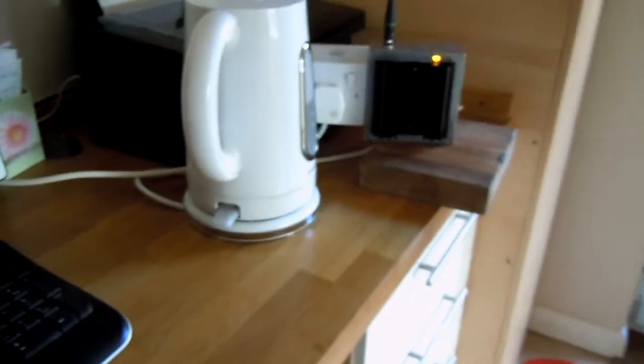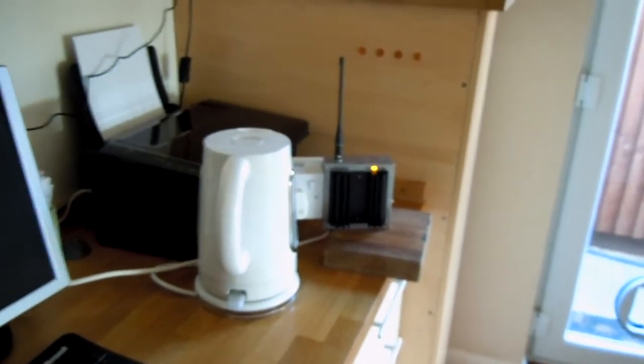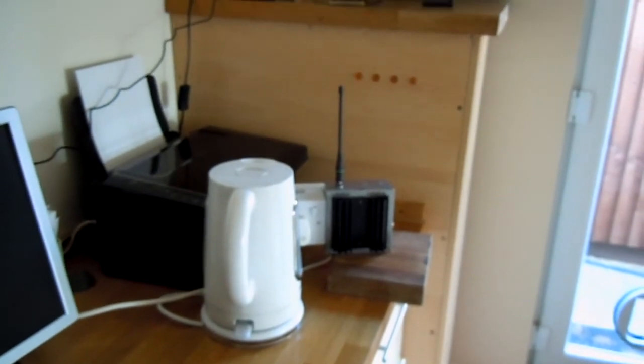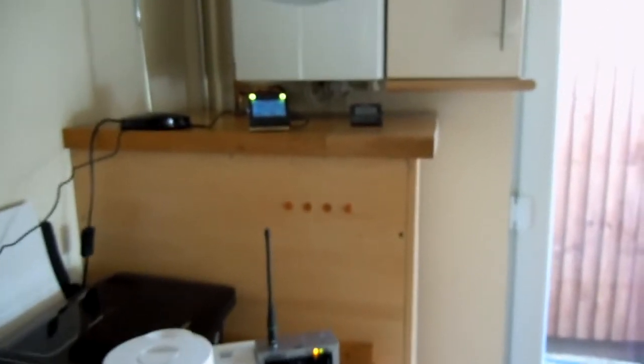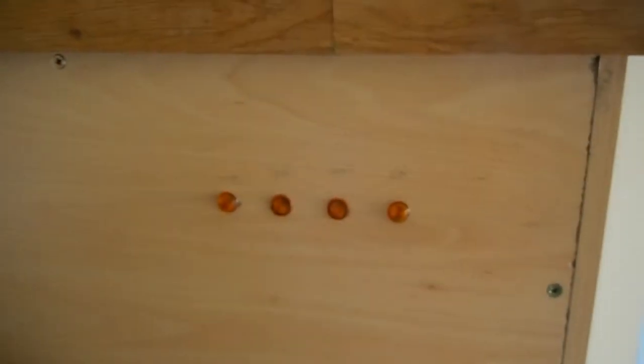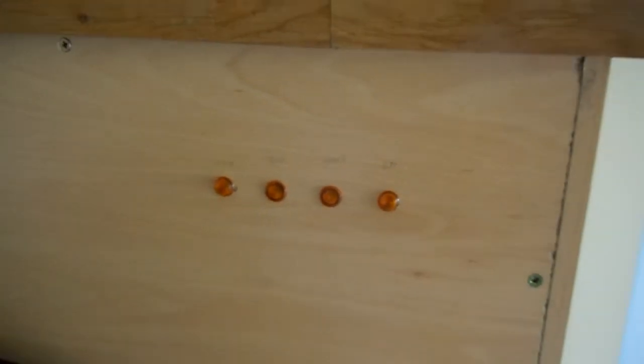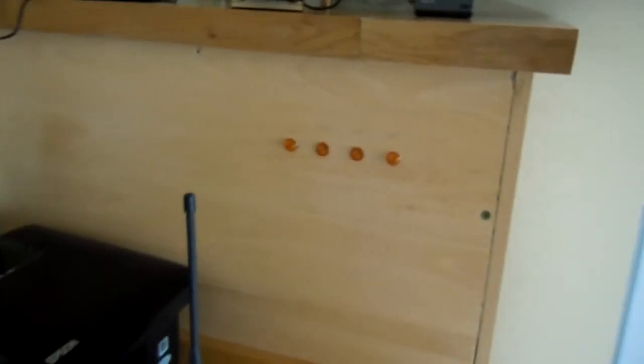what we see, hopefully, washing machine now doing a spin, is that the neons, and the right hand one has also gone out coincidentally, but that's nothing to do with it, is no longer flashing, so the immersion is not taking any power at all.